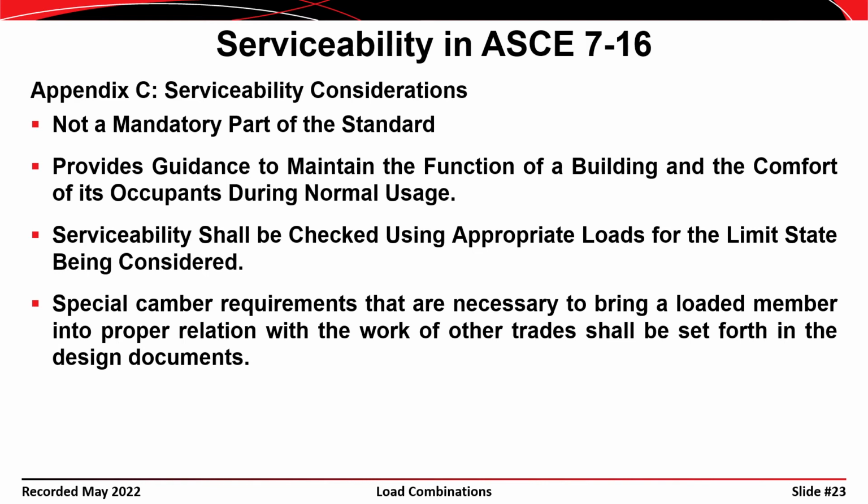That might make the floor unusable. If you had a piece of machinery in there or some equipment that required the floor to be flat, then it would be unworkable. And at best, it's just not a good situation. So typically, we'll camber the beams upward. We'll bend the beams upward so that when the dead loads and maybe a portion of the live loads are applied to the beam, the beam deflects down into a flat position. That's what camber is.